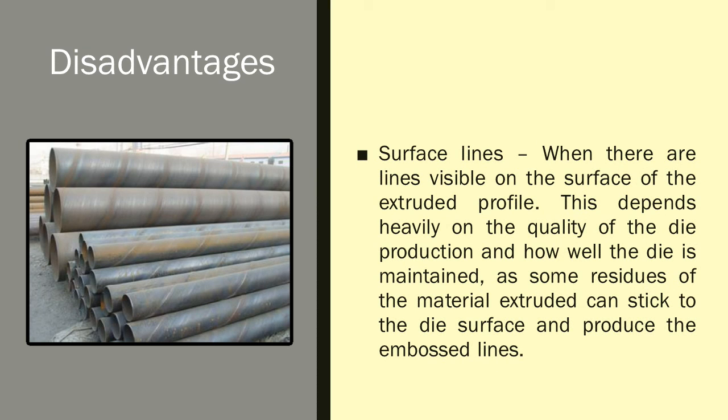Surface lines. When there are lines visible on the surface of the extruded profile, this depends heavily on the quality of the die production and how well the die is maintained, as some residues of materials extruded can stick to the die surface and produce the embossed lines.